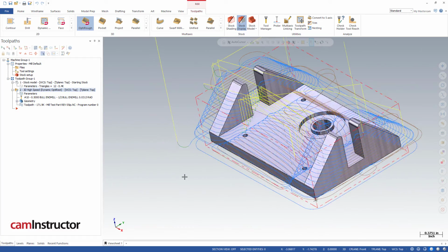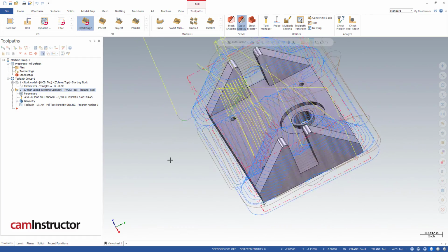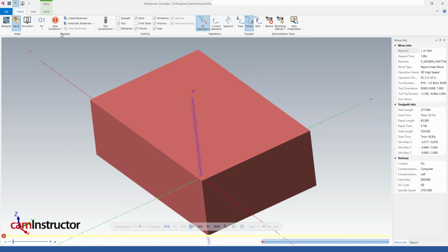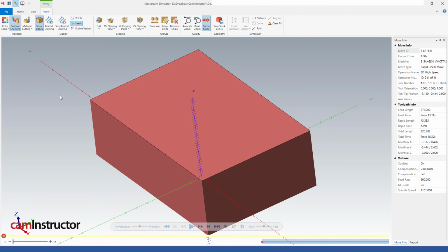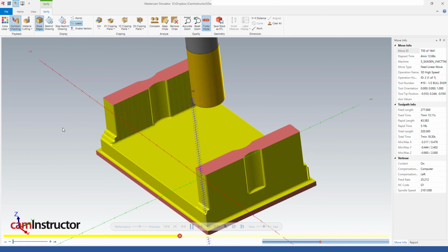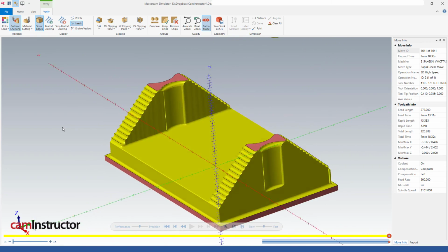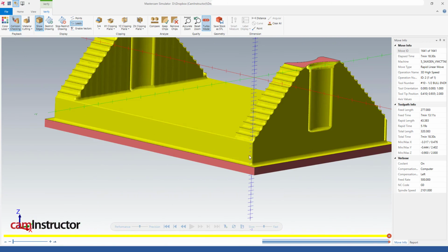So we're happy with the looks of the tool motion on this so far. Let's launch into a verify. Now in verify, I want to make sure I have a stop condition on for collisions. Anytime this tool is detected colliding with our stock, I want it to pause so I know something bad has happened. I'll turn this on over here. Color loop's not going to affect anything because we only have one toolpath. And we'll launch and play through. Everything looks fine there. There were no collisions.